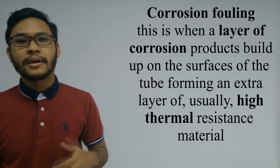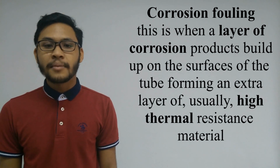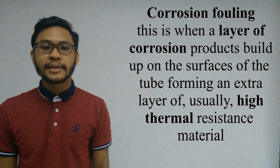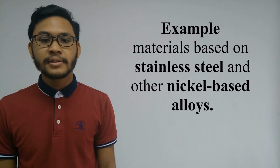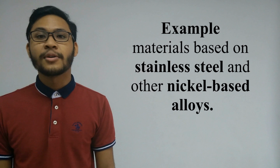Other than that, there is corrosion fouling. This is when a layer of corrosion products build up on the surfaces of the tube, forming an extra layer of usually high thermal resistant material. For example, we can choose corrosion resistant material such as stainless steel and other nickel based alloys.